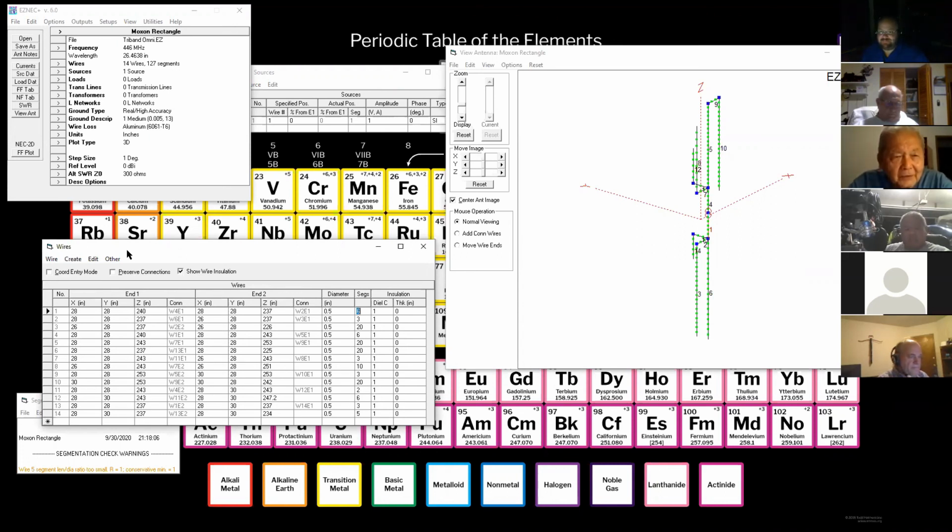So there's a whole bunch of stuff sitting up in the poles right now. And actually, I've used that stuff effectively as balanced line many times, because it is a balanced line. You can use it as a feed line. Oh, okay. So it's like a ladder line. Yep, exactly. But I think its characteristic impedance is closer to something like 75 or 100 ohms, because those wires are really close together. 75 sounds very familiar. Yep.